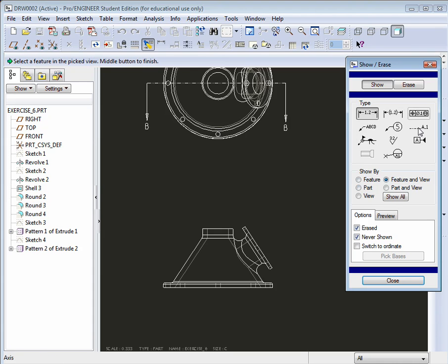And what these are, what you're looking at, are all dimensions and annotations that could have been added into the 3-dimensional model, like surface finish symbols or weldment symbols and things like that, datums. If there are none in the model, then you could just bring up the regular dimensions, which is this one right here versus inspection or reference dimensions. So just make sure that's selected.